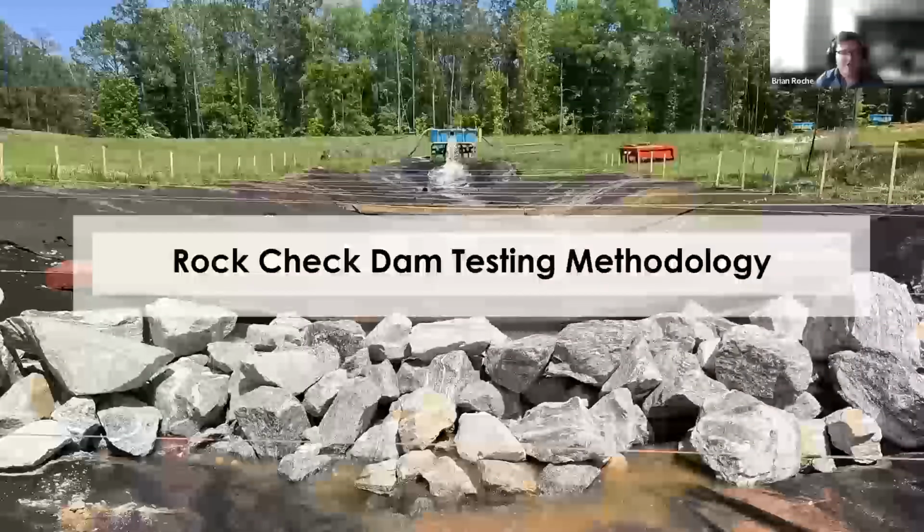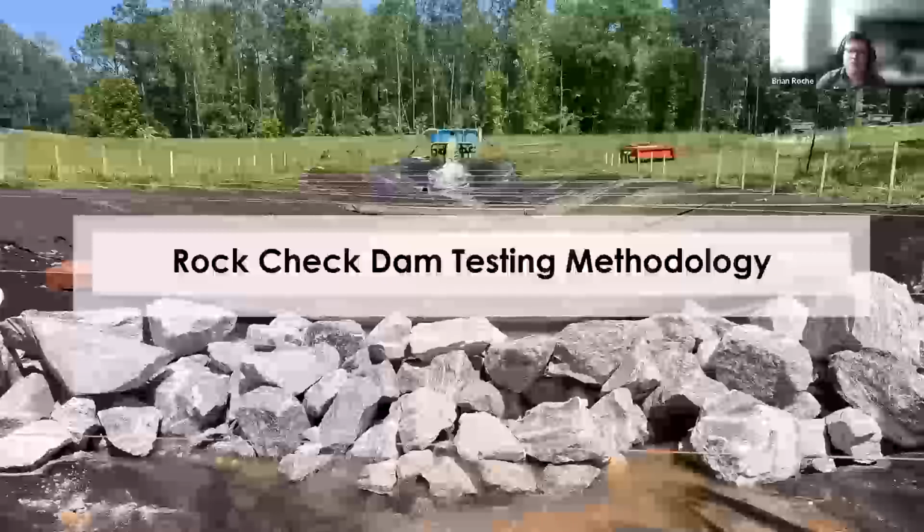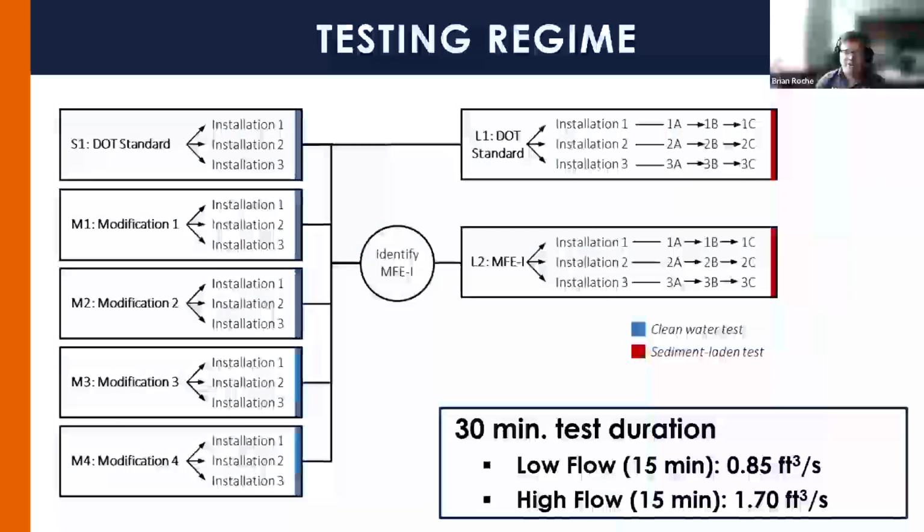Just briefly, we're going to touch on our testing methodology before getting into results. We evaluated a standard installation followed by 7 modifications. Each was evaluated 3 times under a low flow and a high flow. That high flow was representative of 1 acre in Iowa, and that low flow was about half an acre.